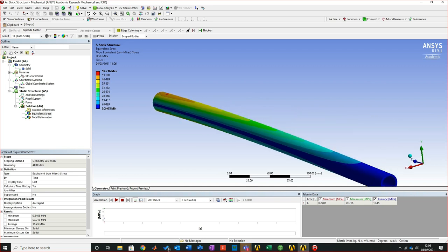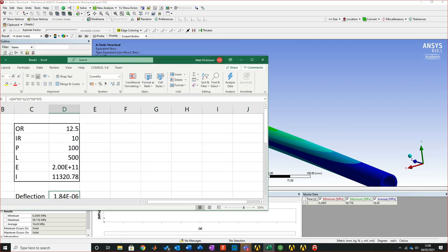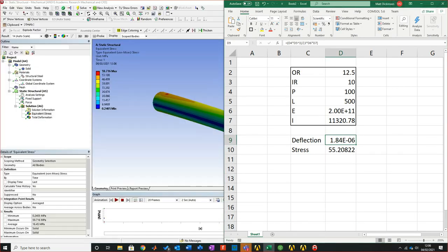If you remember last week, ANSYS will say that we don't know everything. What we're saying is that your error on your maximum value is between 53 and 59 megapascals. And to see if we are in the right ballpark, what we can do is go to 59. Well, we've got 55.2 megapascals, and there confirms that we are right.